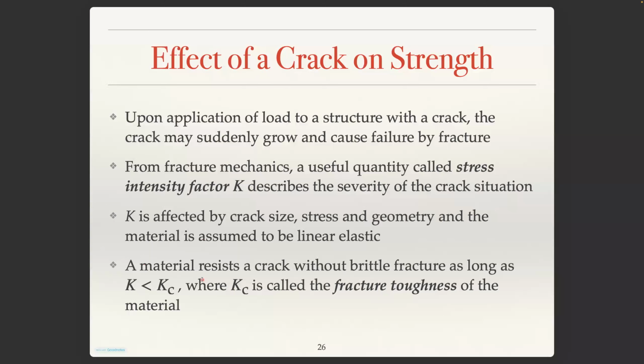Sir, we are only dealing with mode 1, right? Not mode 2, mode 3? In general, this will not be the case, right? No. In general, you will have a mixed mode fracture, but you can also find mixed mode fracture toughness. Similar to what we have for the three-dimensional state, we can generate a similar scenario for fracture problems also.